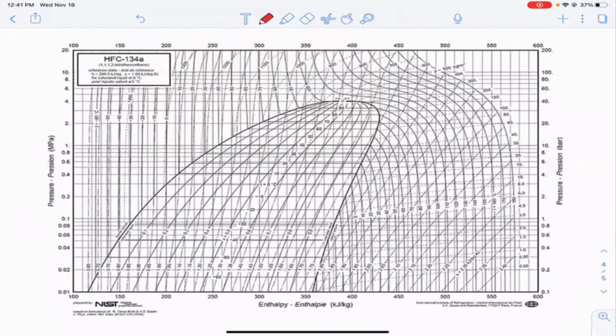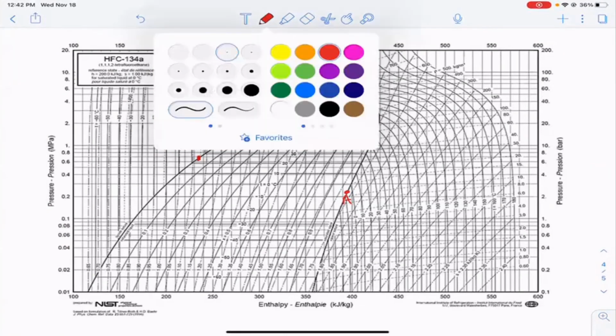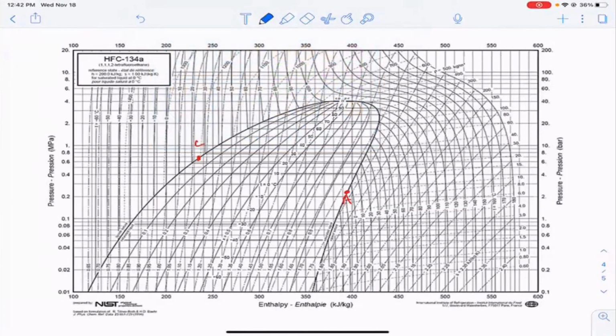If you recall, the temperature of the evaporator is -6, and that's saturated vapor, so that's A, and that's here. And then at 26 degrees, we have saturated liquid, and that is state C. And we'll do the same thing that we did previously, where we'll draw straight horizontal lines so we know what the operating pressures are for this process. Okay. All right, there we go.